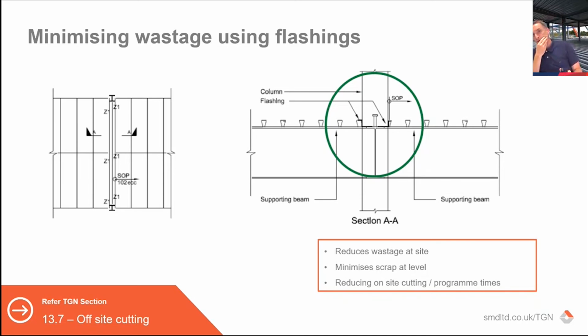Well, on a very thin flange, I would suggest the more robust nail. I can't think of an instance where it's necessarily been raised, not with floor decks, but if you think about the size of the nail and the thickness of the flange, there is potential, because when a shot fired nail is installed, it obviously displaces steel as the nail goes into the beam. On a very thin flange, particularly I would suggest with an EMP, depending how critical it is, you would potentially see very small dimples where those fixings are located. I'm not aware of an issue, and I'm looking at my colleague sitting opposite me, and he's shaking his head. So I'm not aware of an issue, but there is potential for it to show through. It wouldn't pierce through, but you might see a small displacement, on very thin flanges.